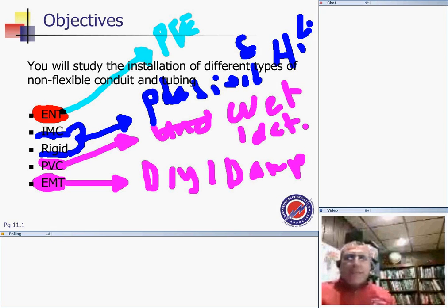And Jacob, my friend, if you are in a highly corrosive environment, like direct buried, wastewater treatment plants, oxidation ditches, lift stations, chemical plants, places that get certain chemicals that eat through metal, like steel and aluminum, your conduit of choice probably would be a non-metallic conduit like PVC or ENT, depending on the application. If you have a highly corrosive environment, which is mostly wet but doesn't have to be, that will be your conduit.